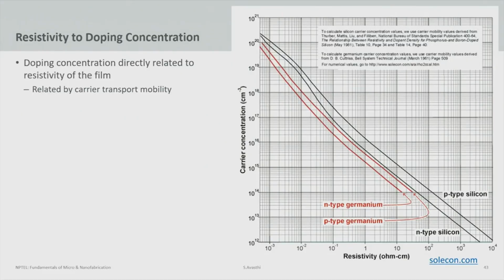However, one thing to note is, in order for this to work, you must know the thickness, and that thickness is often unknown because you do not know how deep your dopants have diffused. So for that, often people use SIMS. Once you know resistivity, however, you can back calculate the doping by the simple graph. So if you measure a resistivity of 10, you just go up, look up whether you have p-type material or n-type material, and that gives you a dopant concentration.